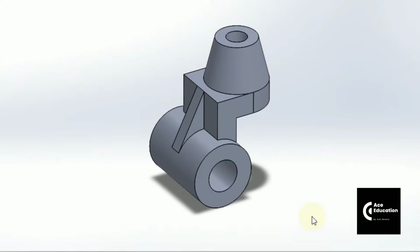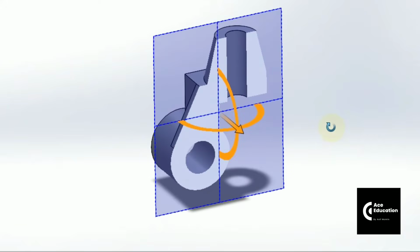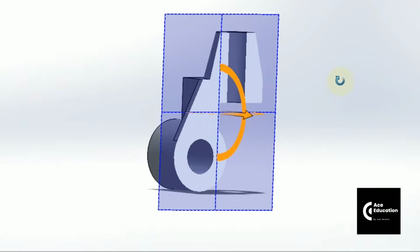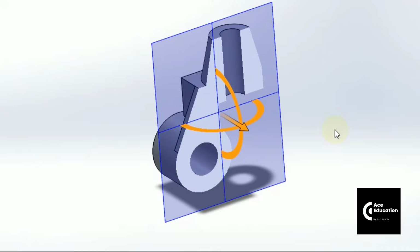But friends, we are going to see how the sectional front view can be drawn for this problem. So we'll be cutting this object from the mid plane so that this object is cut along this plane itself. So you can see here how, after cutting the object from the mid plane, it can be seen. Now wherever the surface is being cut, on that surface itself we are going to show the hatch lines.